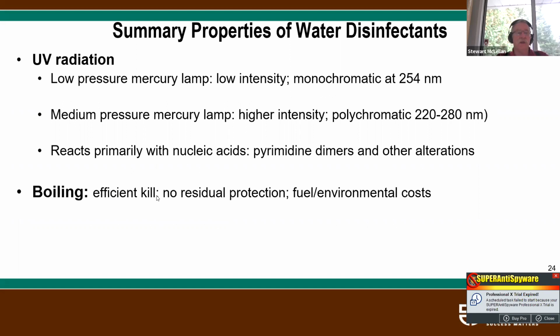Boiling, efficient kill, no residual protection, fuel and environmental costs. So we could always boil water to kill bacteria. Boiling is quite efficient at killing and removal of microbes, but it gives you no residual protection. You can boil water, and if that water remains standing for a period of time, you could have bacteria be reintroduced into the water before the point of use.